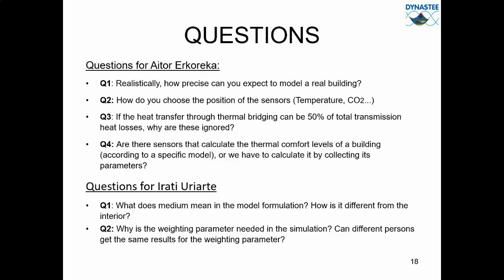So actually the sensors don't directly calculate the thermal comfort level. The sensors measure temperature and relative humidity, and then depending on the activity level and the time you would be using that thermal zone, you will calculate if 95% of the people or 80%, depending on your analysis, a percentage of the people using that thermal zone would be in comfort conditions or not.